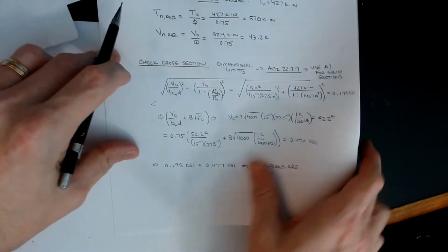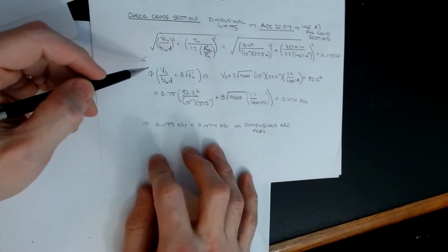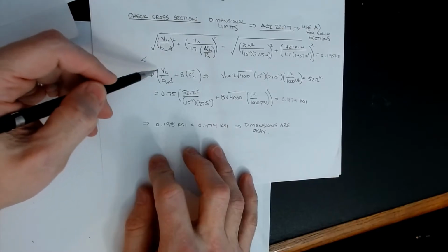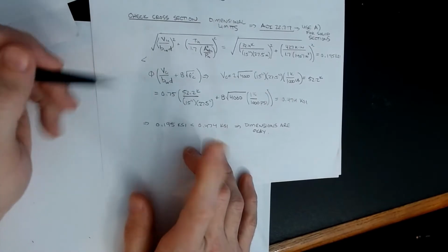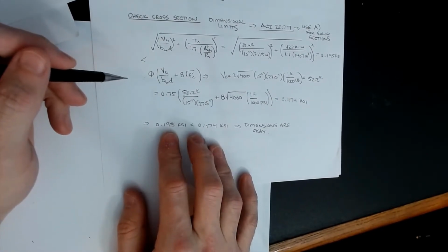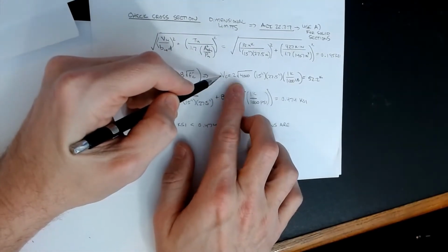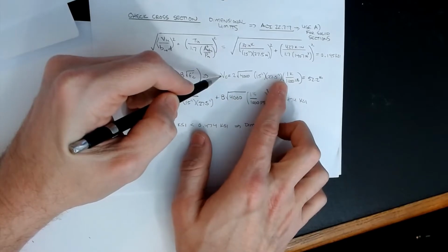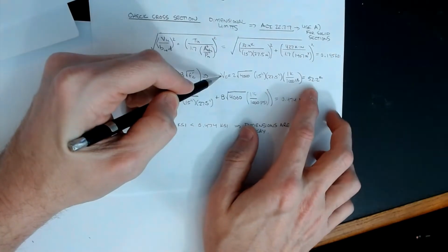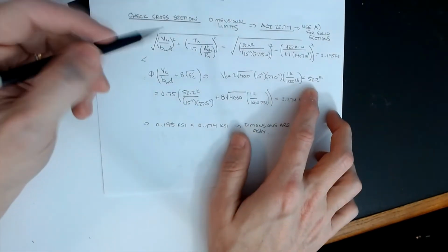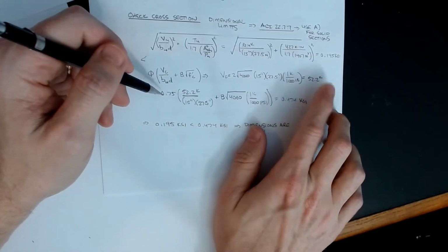Now we've got to figure out, what's the total average stress that the section can support? That formula was the other side of the equation: phi times VC over BWD plus 8 root F prime C. Now again, you've got to watch your units on this. First thing we do is calculate VC. This is the old 2 root F prime C BWD formula that you remembered from shear. So that's no problem. If I plug all of that in, the shear concrete capacity is 52.2 kips. Okay, and so I can plug all of that in. We've got to watch our units. The units on this are kips.